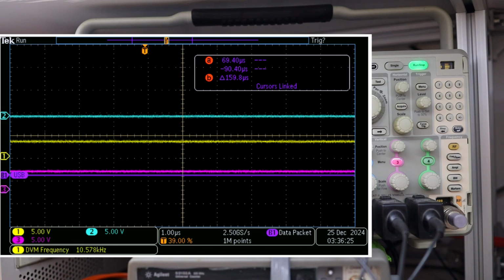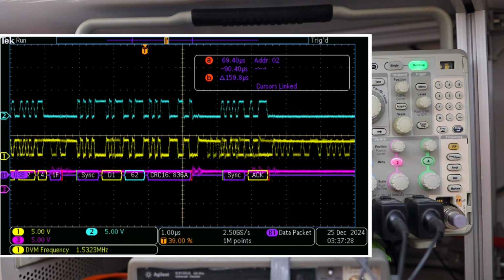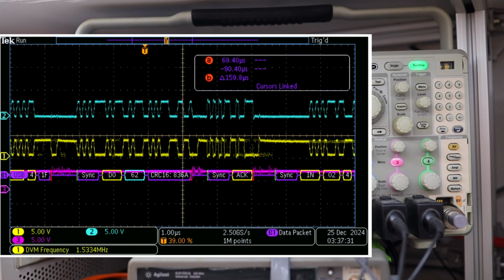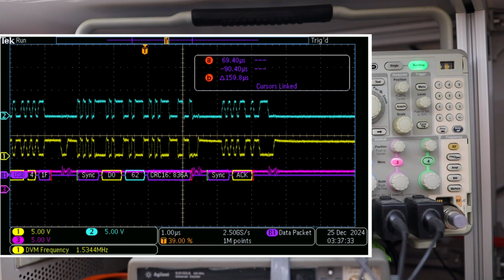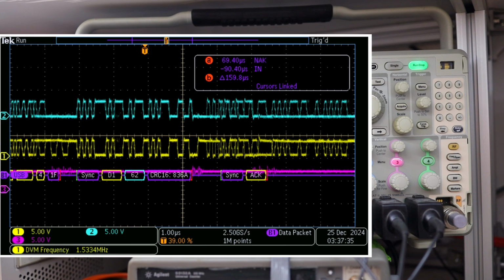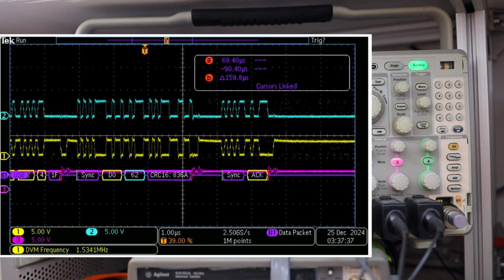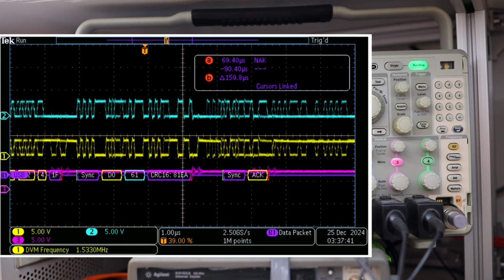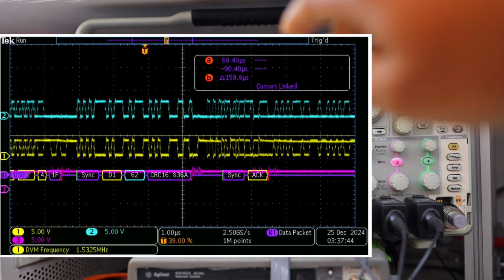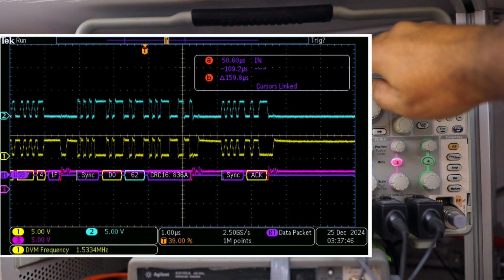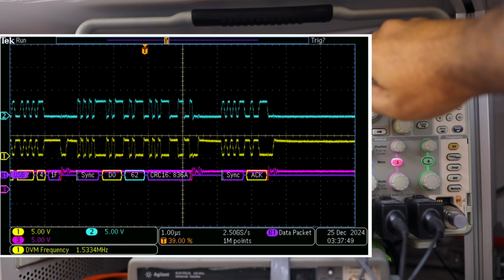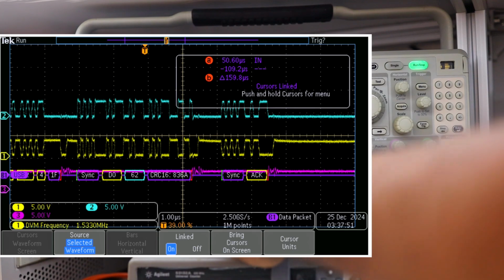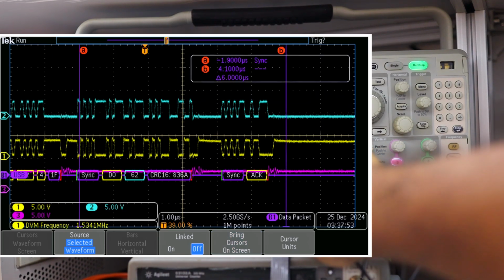I'll send some UART packets and we'll see if the packets first of all get detected on the USB and then second detected on the UART as well. You see, I'm sending a character. The character is just B, ASCII B, and you see that 62. Let me send an A. It should be 61. Yeah, now it's 61. B is 62. You see that? I'll maybe place the cursor, then you will see it better. Let's bring the cursor back onto the screen.